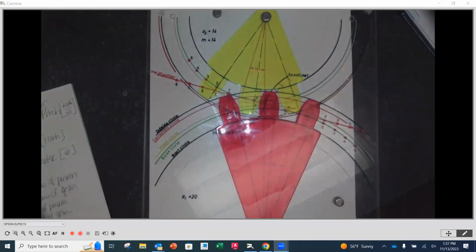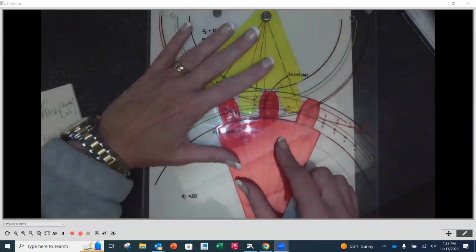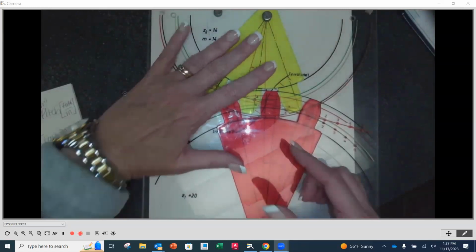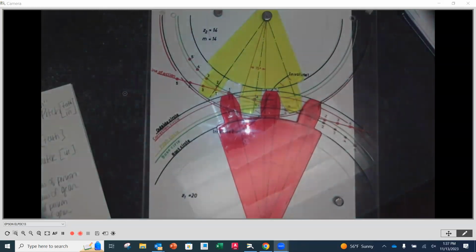This is a place for that oil lubrication to get into so that we can, number one, reduce the amount of heat from friction. We can pull that away as things hit each other. It keeps the noise down, and the wear over time as well. So if we keep it nicely lubricated, it's going to last longer. And this backlash, this space in between, gives that lubrication someplace to be as well. Because if we were metal on metal, it's noisy and there's going to be a lot of heat.